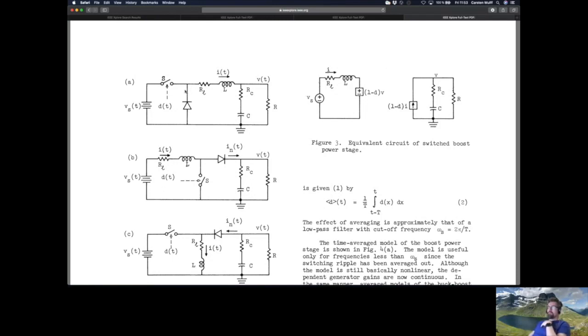And the really neat trick about these types of converters is that they convert power consumption on this side to power consumption on the battery. So if you spend 1 milliamp at 1 volt and you have a 3 volt battery, it actually turns into 0.3 milliamps. So you divide by the voltage ratio, and that's really nice in integrated circuits.